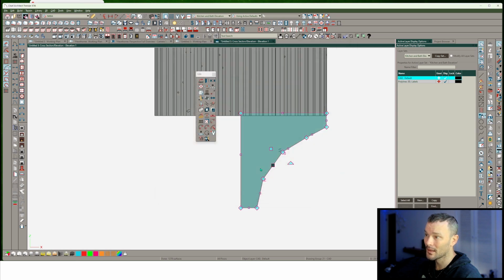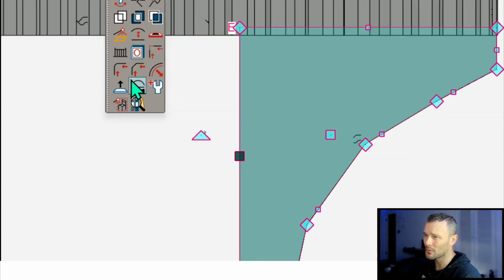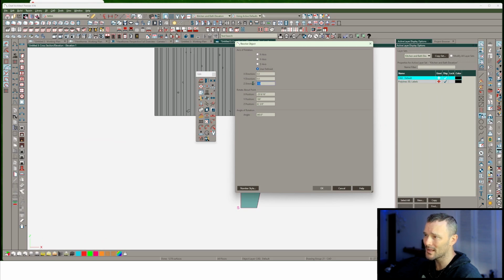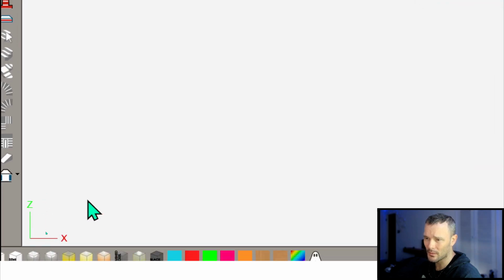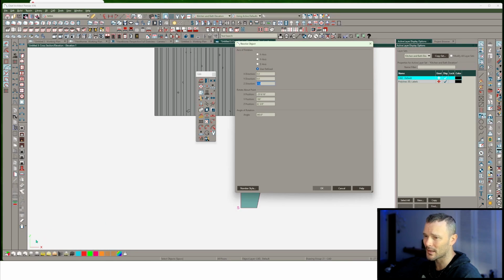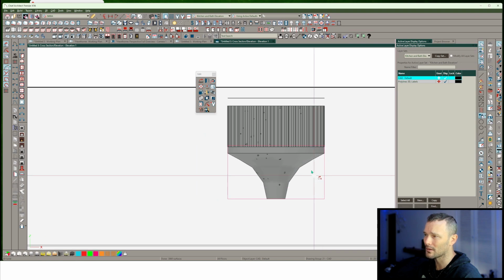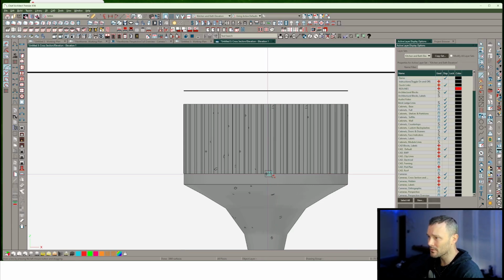Now from this point, I'm going to click on this edit handle, and I'm going to use the revolve object. And we're going to revolve in the Z-axis. You notice here at the bottom of the screen, that's the Z-axis. We want to spin around that axis, right, as if it was a spindle. So there's that Z direction, Z-axis. We're going to spin it 360 degrees. Bam. That'll get us this right there. Isn't that cool?